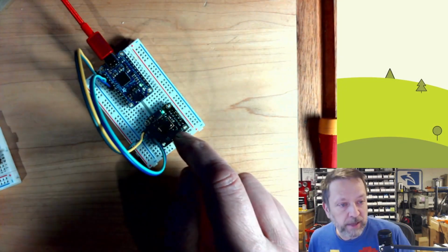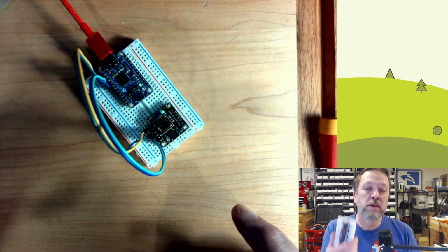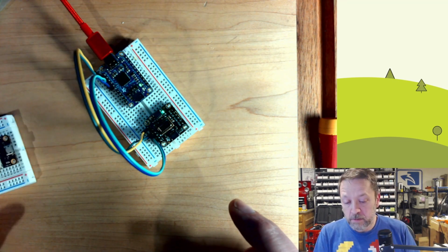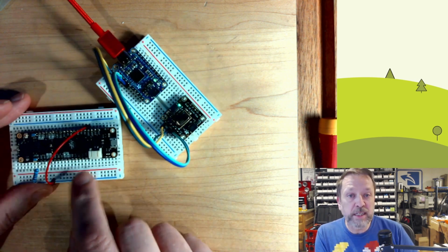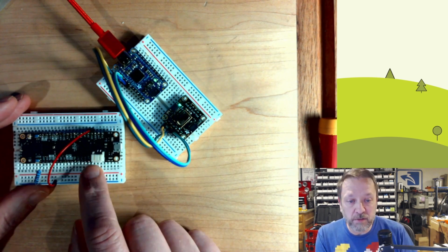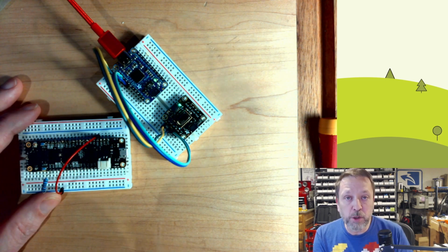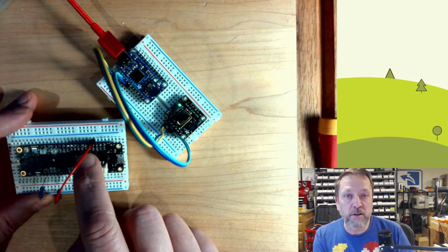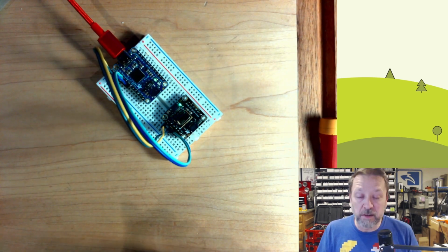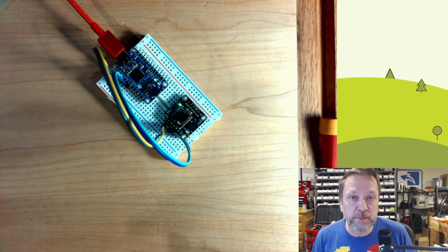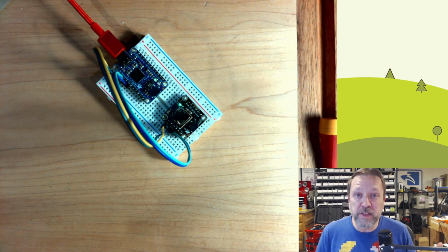So if you take a look, I've got that same module here. Now, to do the development, I could do this development on the F7 hardware. I don't like doing that because the deployment time to something like this F7 is very slow. It's embedded, right? In order to do any development, I have to write the code and then push it from my PC down to the hardware, and then get the result via console or debug. I usually don't use the debugger even on that because the step time just tends to be slow. I prefer something a lot faster, something that is more modern in feel.